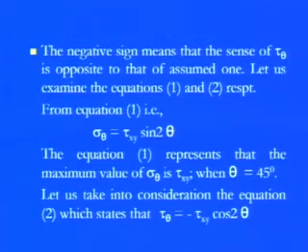If the shear stress is there, tau theta is equal to minus tau xy cos of 2 theta. The negative sign means that, as I told you, the sense of tau theta is opposite to the assumed one. So if you are not concerned about the complementary shear stresses, then you cannot say that the element you have chosen is in equilibrium under the applied stress. So we always need to assume that the applied stresses are along the parallel axes, but on the other side we have the complementary shear stresses which balance these stresses.